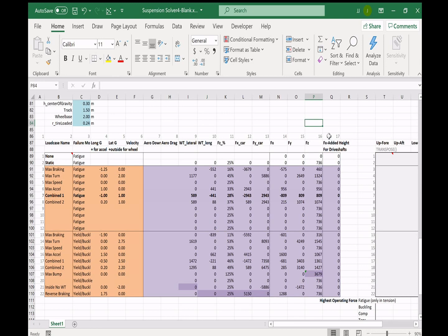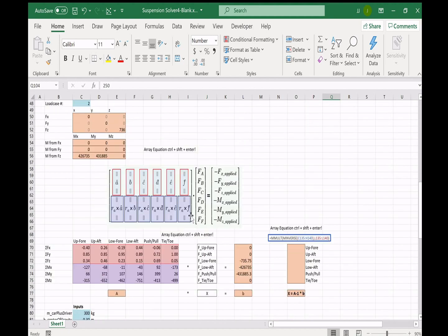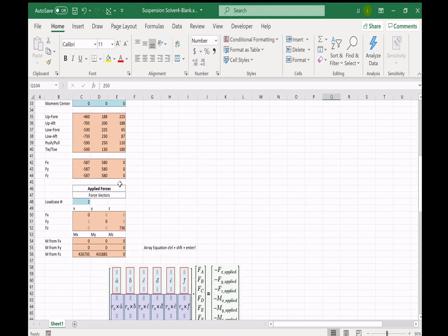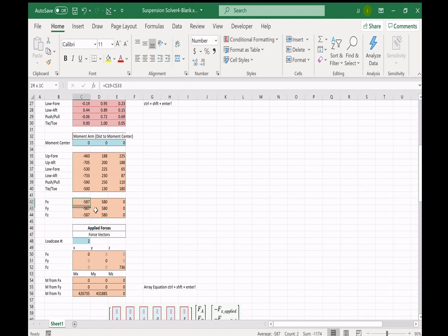So this is the front of the vehicle, so we won't have any adjustments because the front wheels do not have drive shafts attached to them, so there will never be torque going through them. But if we were doing the rear, then for maximum acceleration, in this case, we'd add in 250 millimeters.